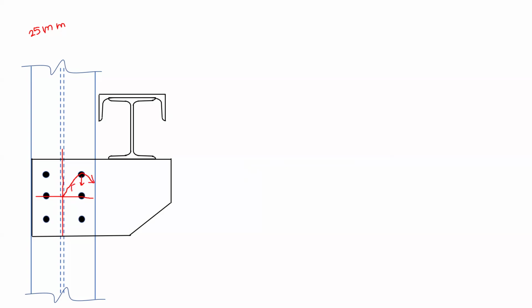So we have, this is force due to axial value, and we have force which is due to moment, and then we have to find value of a resultant Fr, and that resultant value should be less than your bolt value, and therefore we have to find bolt value. So this R is the distance connecting CG of bolt group and center of the bolt, and Fm force is perpendicular to this line.